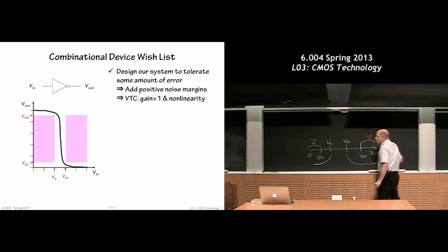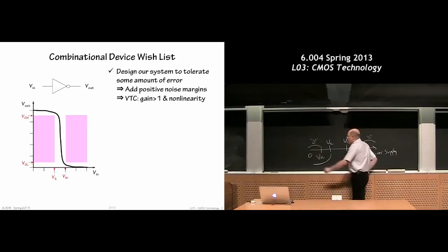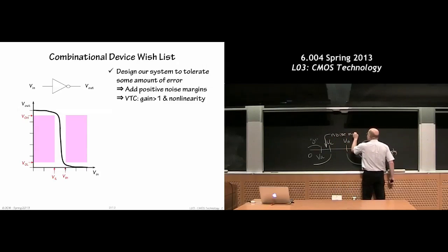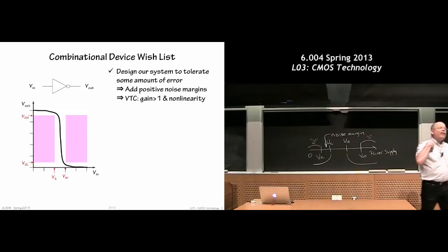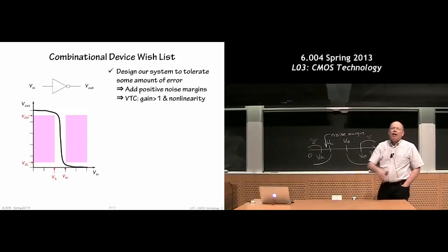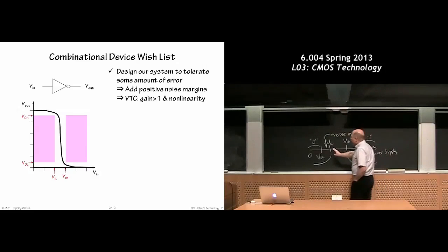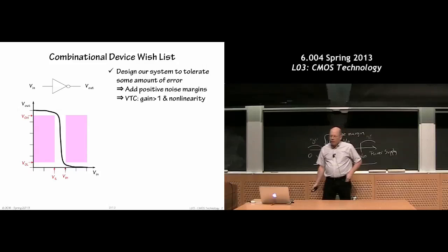Okay, so these were the range of voltages that were considered inputs. And the difference between the output, if I'm sending information to you, between what I have to output and what you accept as inputs, this is called the noise margin. And the noise margin was very important to us because it was our ability to restore slightly flaky signals as they traveled from the output of one device to the input to the next device. Our ability to restore those values back to something that didn't have the noise, that's what made digital systems allow us to have this tinker-toy principle.